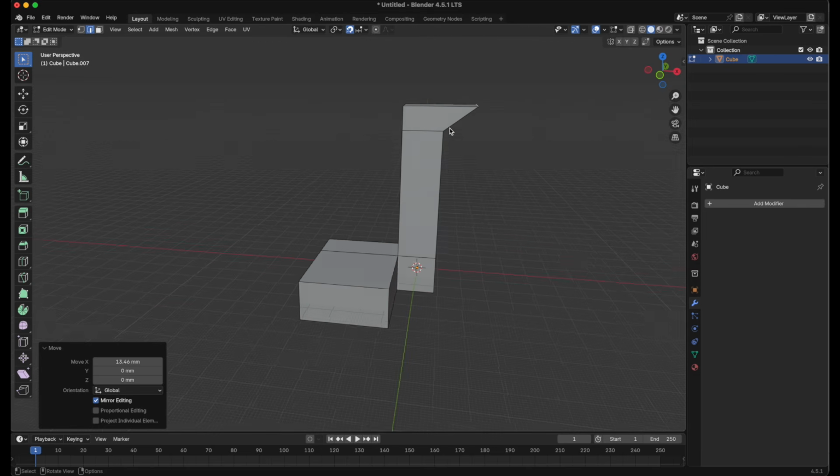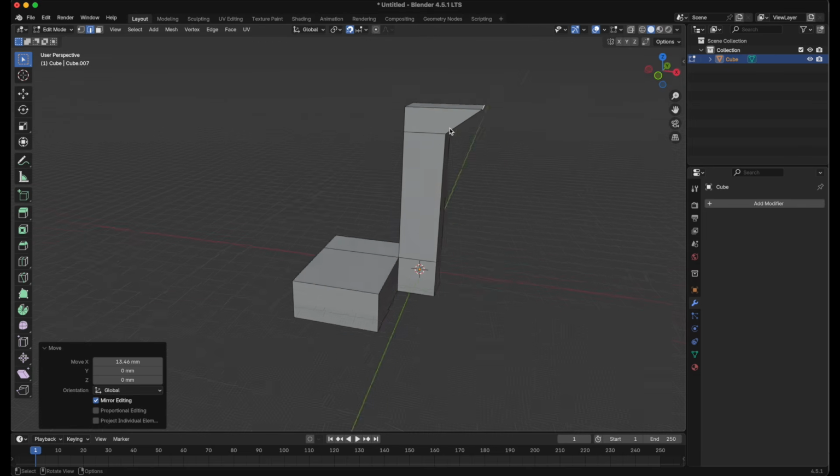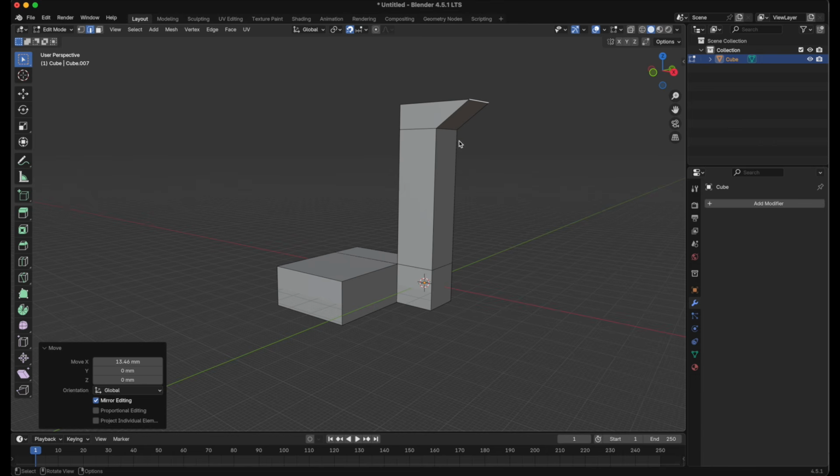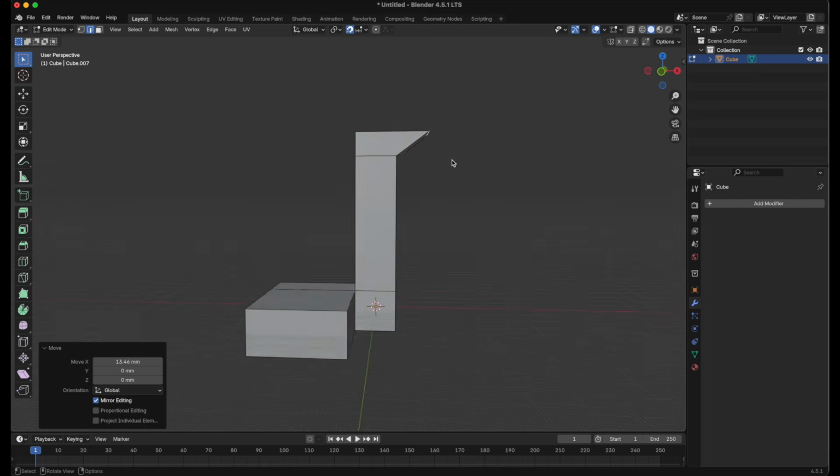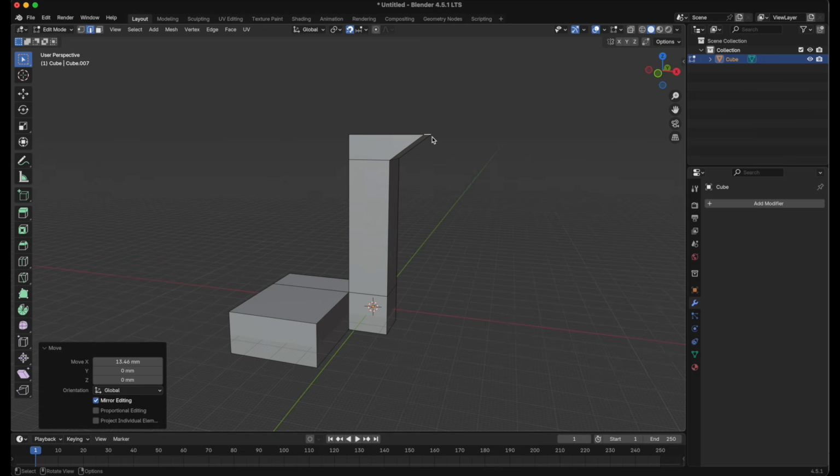bottom surface here, you don't really want to go much over 45 degrees for this overhang. So when you're designing parts for 3D printing and you don't want to have to use support material, because support material can be very annoying, just know that the steepest you can really go on the overhang is about 60 degrees, and you really want to hover around 45 degrees max.